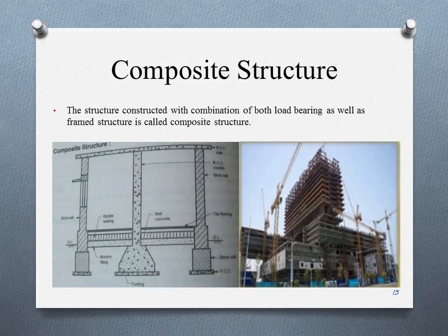Here the load of slab is transmitted to the subsoil by this external walls, that is the load bearing walls, and even through the intermediate, that is the column, through the foundations. This type of construction is generally adopted for industrial sheds, workshop halls, and godowns.